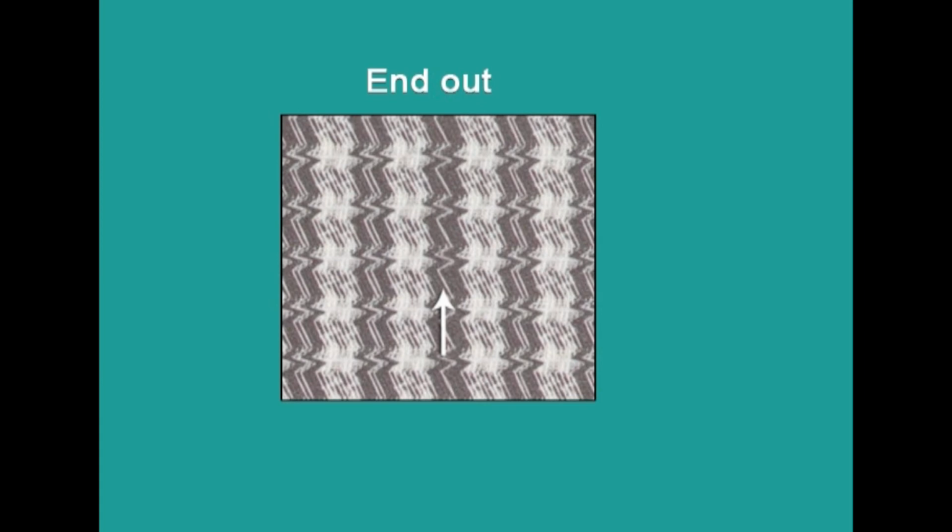And end out, this is caused by yarn breaking and the loom continuing to run with the missing end. Major jerking is caused by the extra piece of filling yarn being jerked part way into the fabric by the shuttle. The defect will appear at the selvage. If it is only at the selvage, sometimes for garments which are not that qualitative, maybe they will take it as a minor, but unless in better quality and other things, definitely it is treated as a major defect.